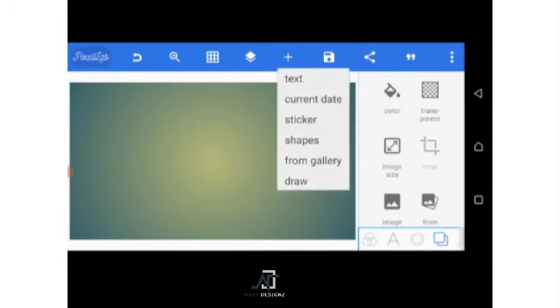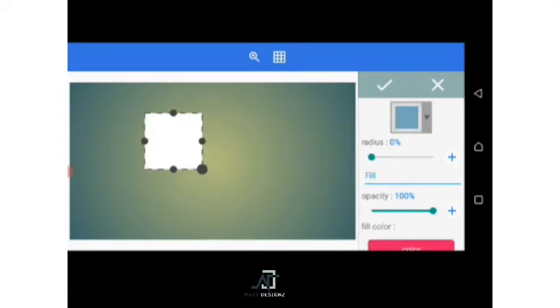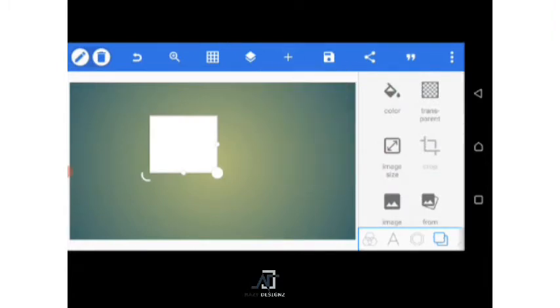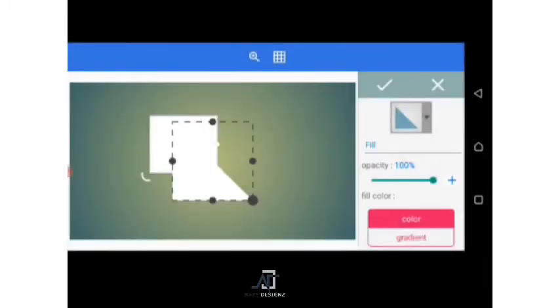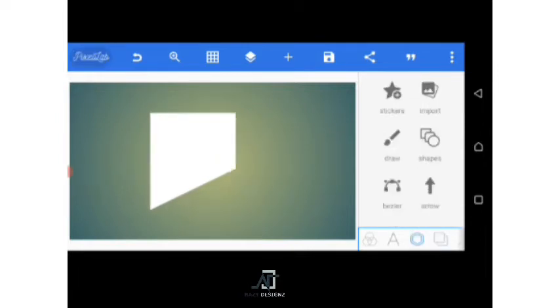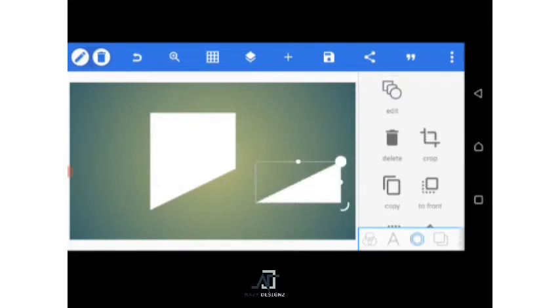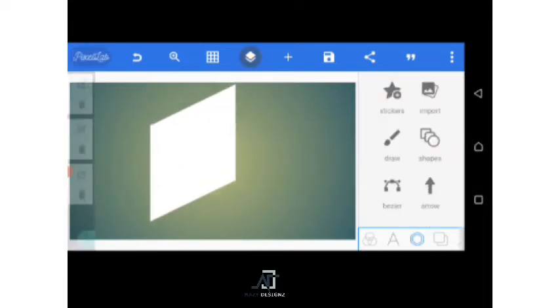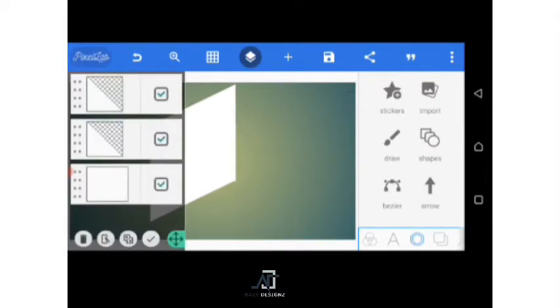So without wasting time, we click on this to import our shape. This is good. Import the shape, click OK. We go back, import another shape, this, click OK. Then we're going to rotate 90 degrees, reduce the height. Then we can drag this, then I click on these and duplicate, then I rotate, I drag it here. We can now go to mesh tool and merge the three items together, the three shapes.